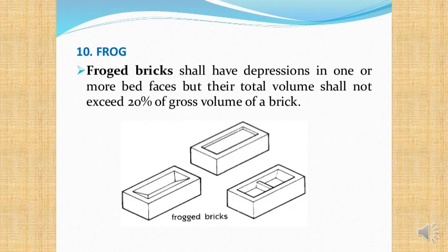And so having frogs or having hollow blocks is a way to reduce the weight so one man can still handle it while not affecting the actual volume or surface area of the block. So you don't have to increase the number of blocks you're having to put together.